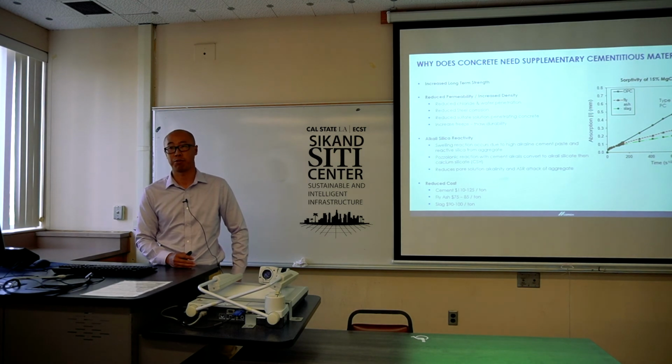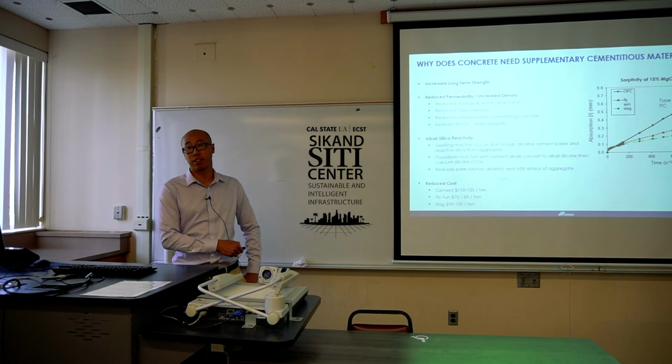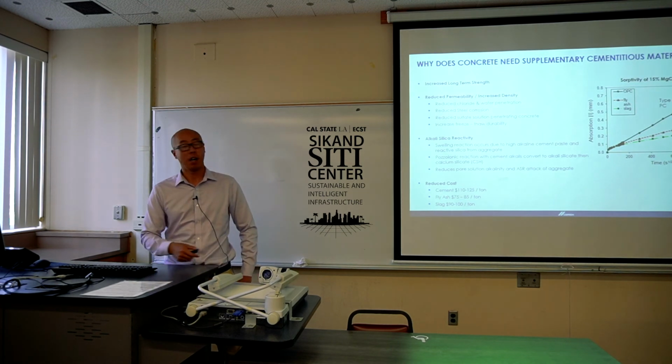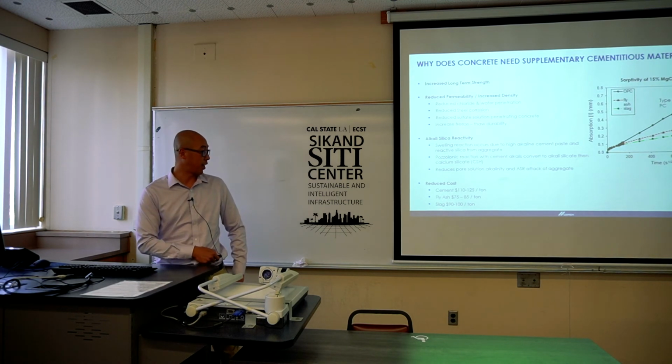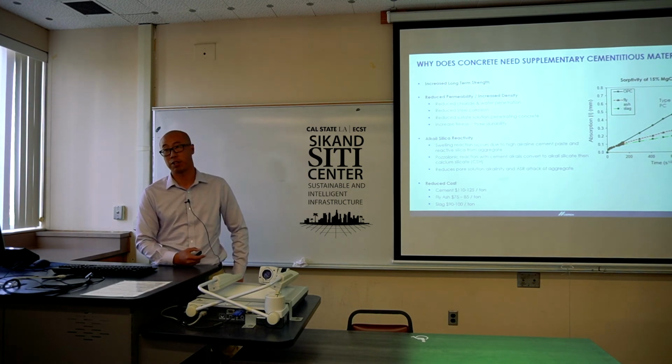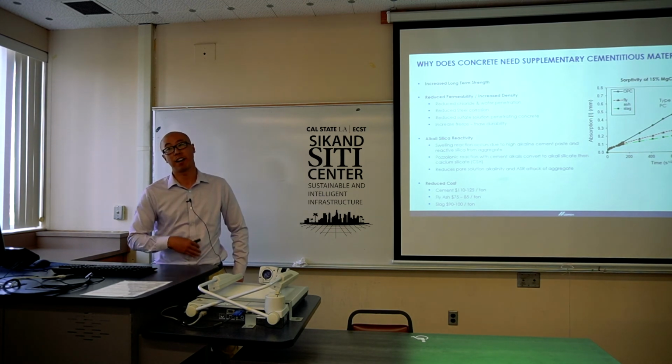It's very hard to find fly ash. But slag is cheaper than cement. Another thing is that for fly ash, you may replace maybe 50%, but for slag, you can replace like 70 to 80%, because slag is more similar to cement, and you can add a higher percentage and reduce the cost of your concrete mix.